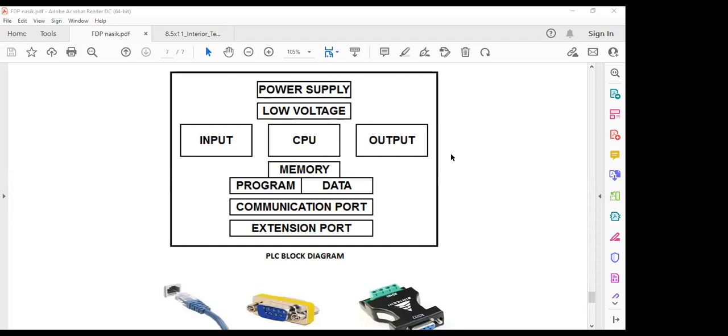In college, we use a stepper for the same application. In industry, it is a servo motor. When you see a Mitsubishi servo motor, I have seen it had 136,000 pulses for one rotation. So high frequency pulses will be required. There you have to use transistor type. So it is clear. Let me move on.